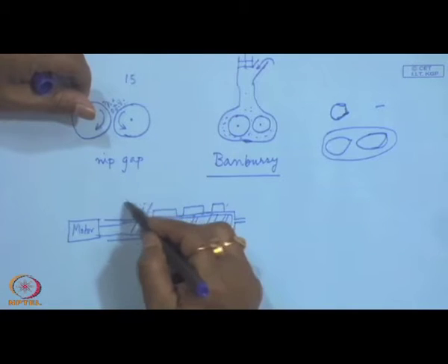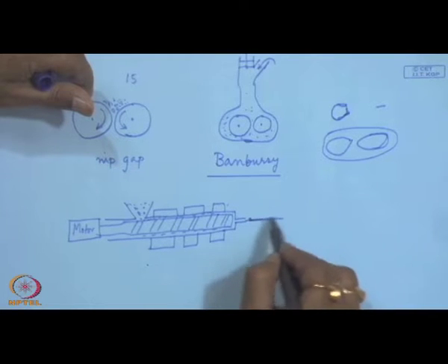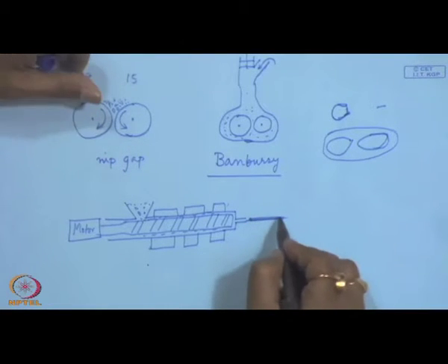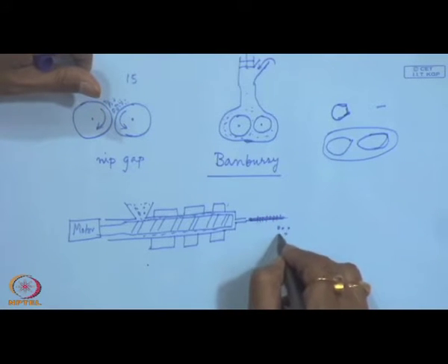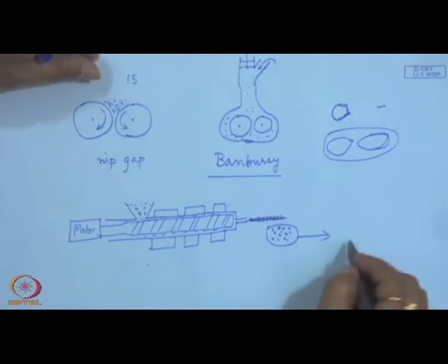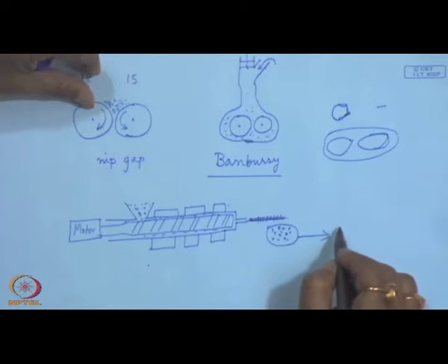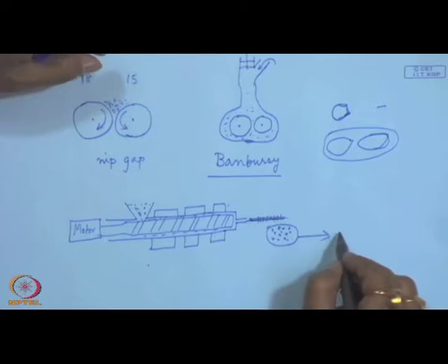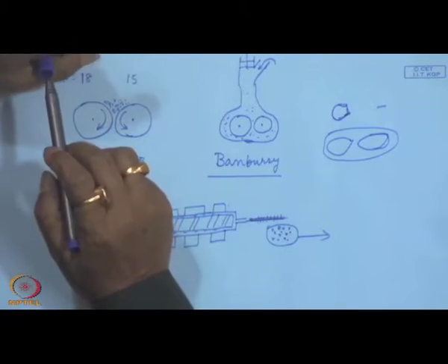Continuously polymer is fed to the extruder through the hopper, and continuously after mixing it comes out and can be chopped to form mixed polymer granules. In the form of granules or tablets or rods we can have the blended polymer. Then this can be further used for subsequent processes to make different types of products, say injection molding of products, or extrusion of pipes or tubes or insulation and covering of electrical conductors.